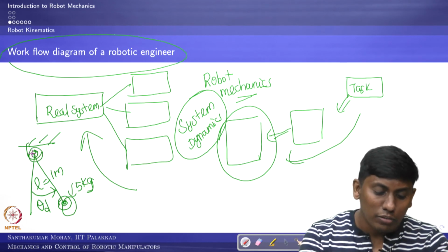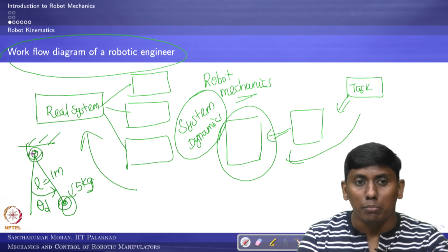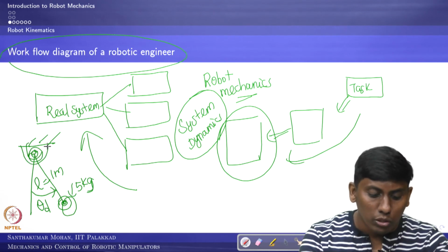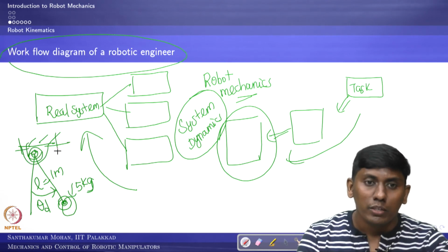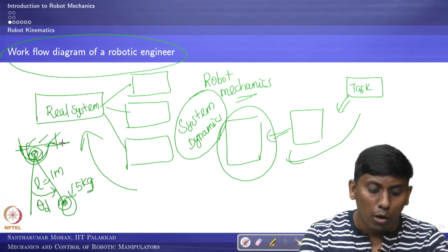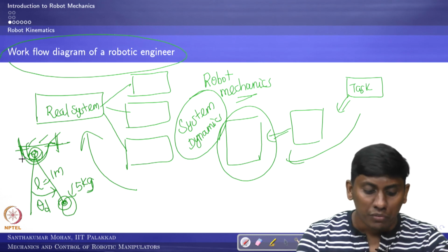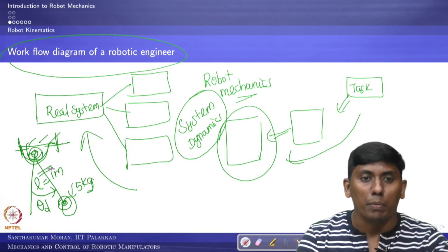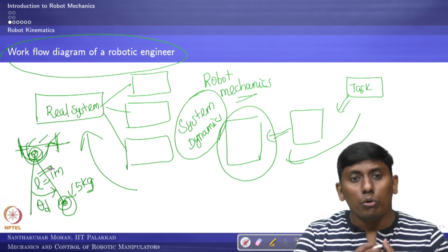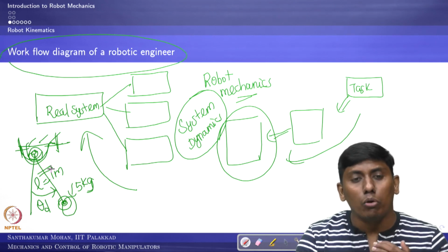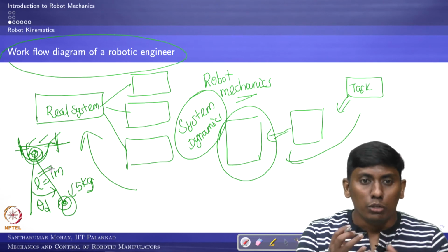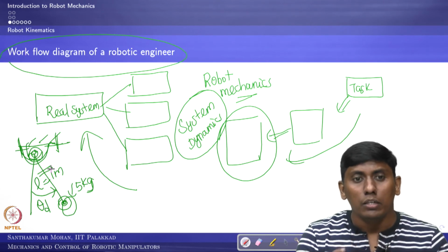Similarly, for this actuator you have to see what the minimum torque would be, and this support you cannot simply glue. You have to work out the proper support so that you can put in a bearing and proper fasteners and everything. Similarly, this needs a proper cross section and material. So you need detail about each and everything. You need to fulfill your motion requirement, and you should fulfill your structural requirement, right?